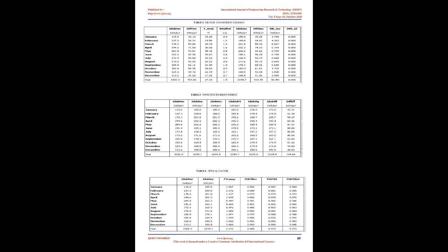It may namely affect the real performance with respect to the final factory flash tests data delivered by some PV module providers. LID loss factor, 0.0%. String voltage mismatch.